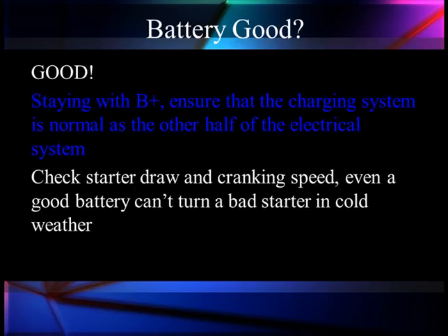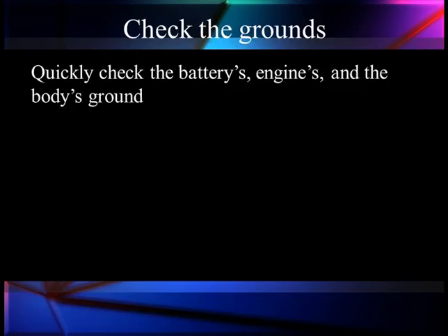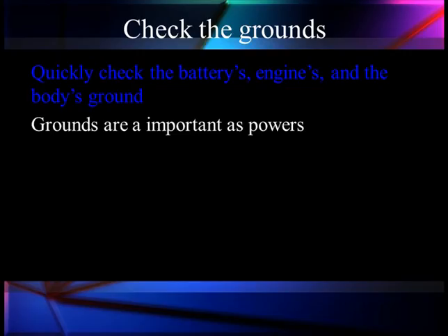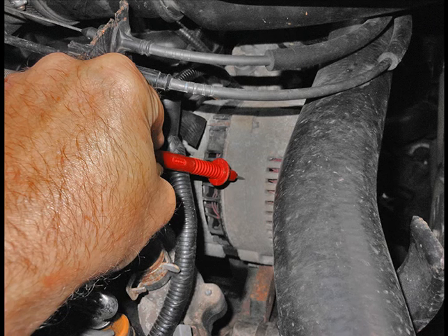Check the starter draw and cranking speed. Even a good battery can't start a bad starter in cold weather, as we've talked about before. Check the grounds. Quickly check the batteries, the engine, and the body grounds. And we'll do it during our test procedure as well. Grounds are just as important as power. Don't misunderstand that. They can be tested quickly enough, which gets all of them out of the way, and it's done and over with, and we can go on.